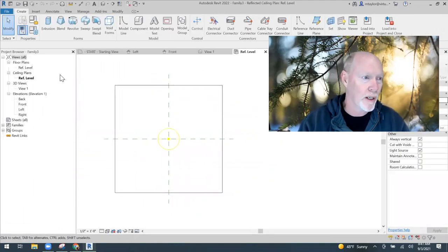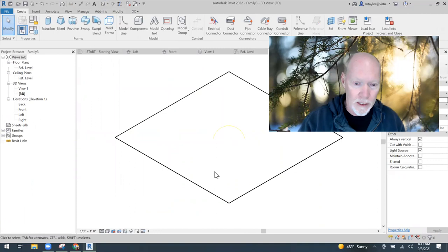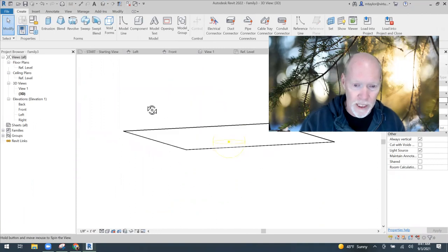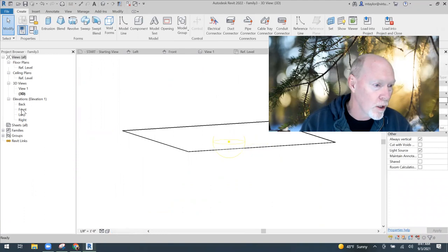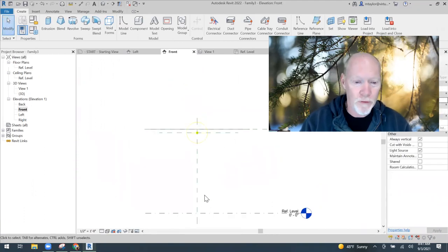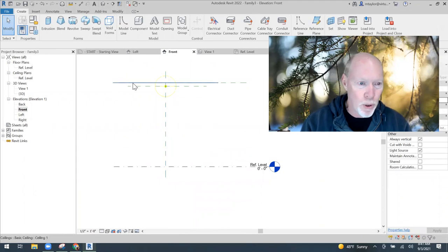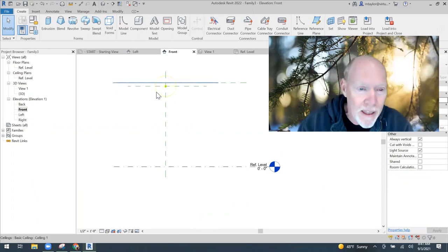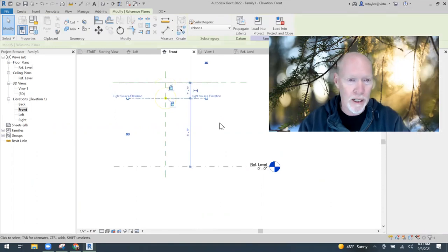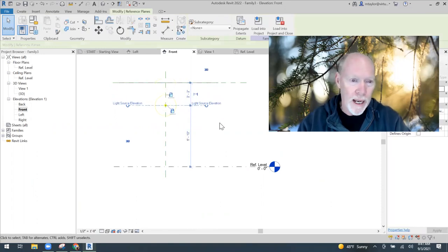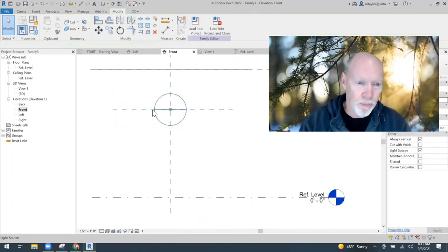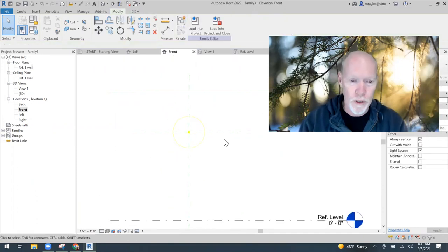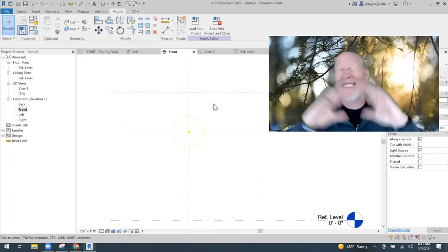This is the ceiling object right here. And if I go to like 3D in this view, and I'm going to orbit around, this is what they give us, okay? So let's go to the front view of this thing. What it is, the floor is down here. They've put in a ceiling that our fixture will stick to, and they've put in a light source. And so I'm just going to click on this light source, and I'm going to move it down a couple feet. 2'6" is plenty. So our light source is down 2'6" from the ceiling. Whatever, it doesn't even matter.